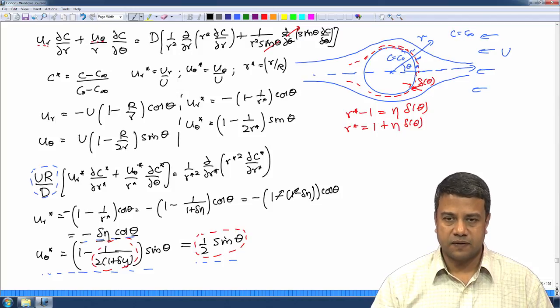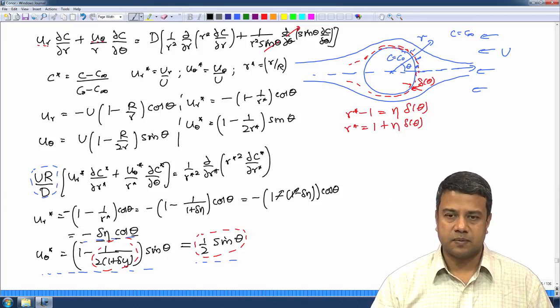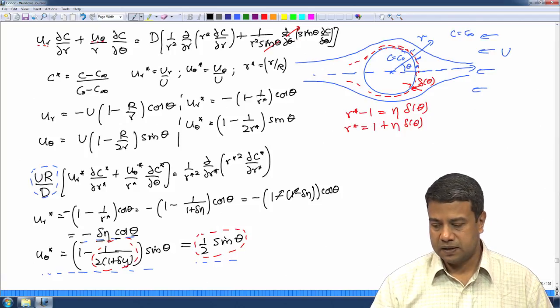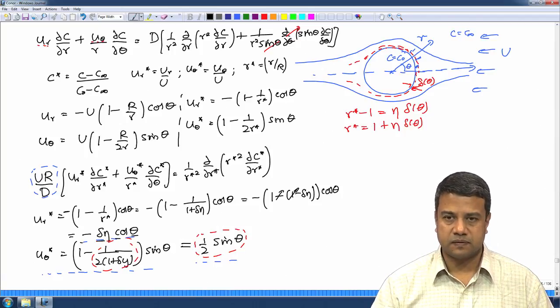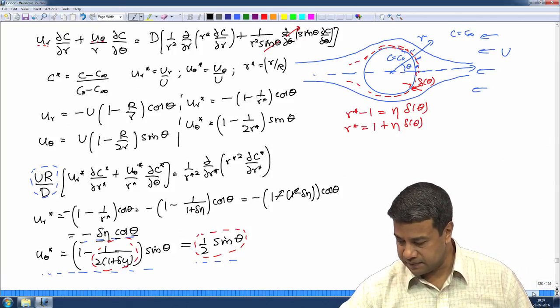Similarly, the flux, which scales as the gradient of the temperature, is inversely proportional to the boundary layer thickness. So, the Nusselt number or the Sherwood number will scale as Peclet number to the plus 1/3 power for flow past surfaces with a no slip condition, and to the plus 1/2 power for flow past surfaces where there is a zero shear stress condition at the surface.